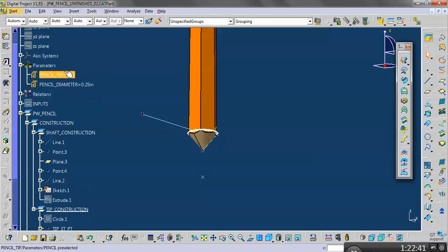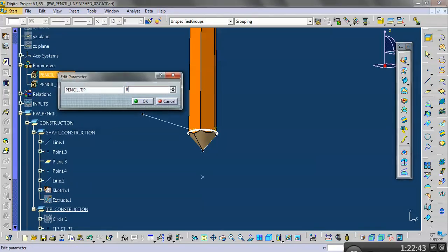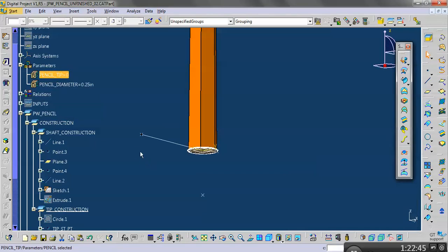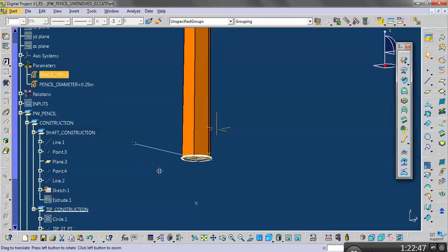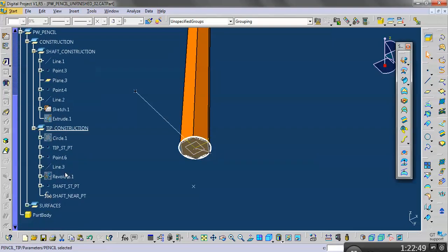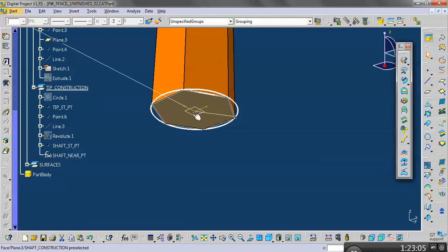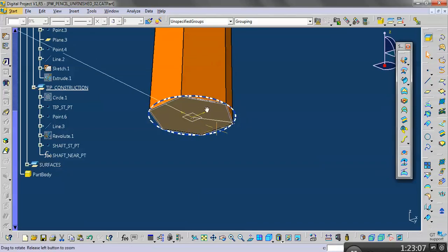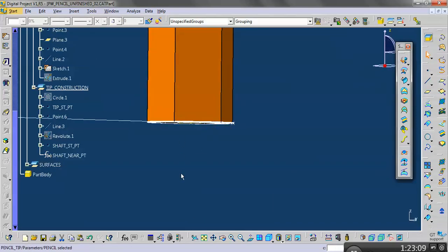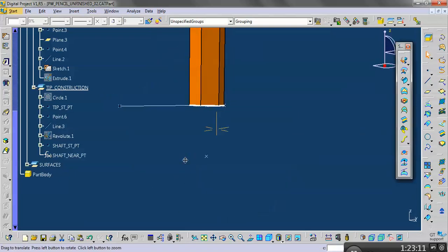And now, if we go to pencil tip 0, we don't get an error anymore, because the split surfaces are still intersecting. Before, they weren't intersecting because the geometry wasn't working right together. But now that we've set it so that this line can flatten based on proximity to the sketch, it works.